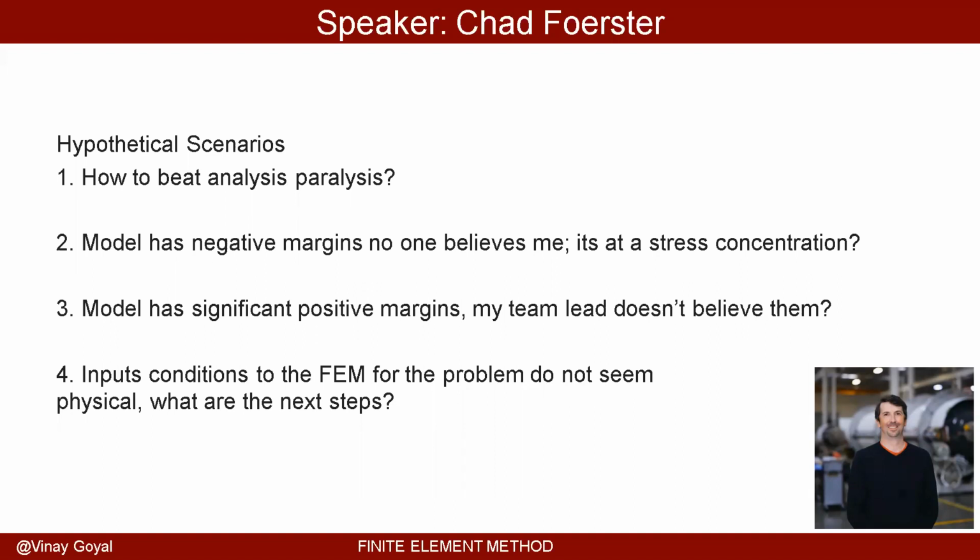And then on the side, I would look at trying to reduce the model, and I would attack it from both ends, right? Because that's the brute force method, with solid elements and a refined mesh and really tackling all those fillets. You might create something that takes an hour to run, but you just let it run on the side. I know that's energy, it's not free per se, but it is working in parallel to you. The next one is going the other way.